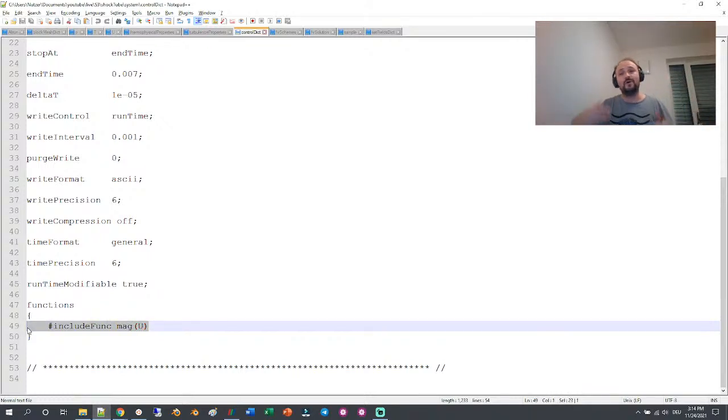Of course, Paraview automatically calculates the magnitude, so it visualizes it, but it's still a pain if you want to use the calculator and use the velocity in the calculator. We will do that because we want to plot the magnitude of the velocity later on in post-processing. So this is why we calculate it.